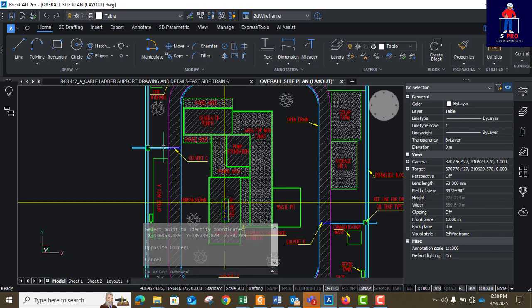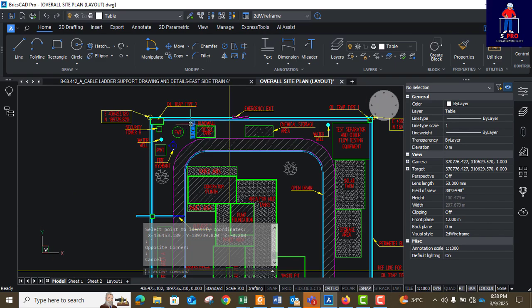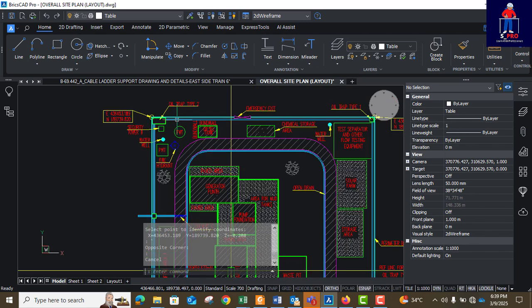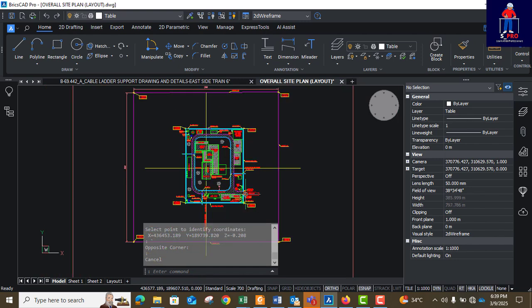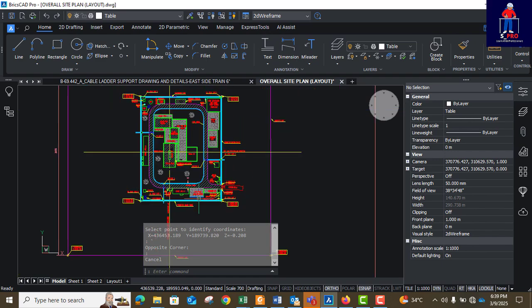Okay, so after that, the drainage, we also have perimeter drain. Of course, if you have designed drainage before, it has to do with catchment areas. So we have this other area here, this catchment area outside the internal road. That one cannot just be running freely, so it should be channeled into a drain, and from there leave the facility. So we have a perimeter drain right around the facility.